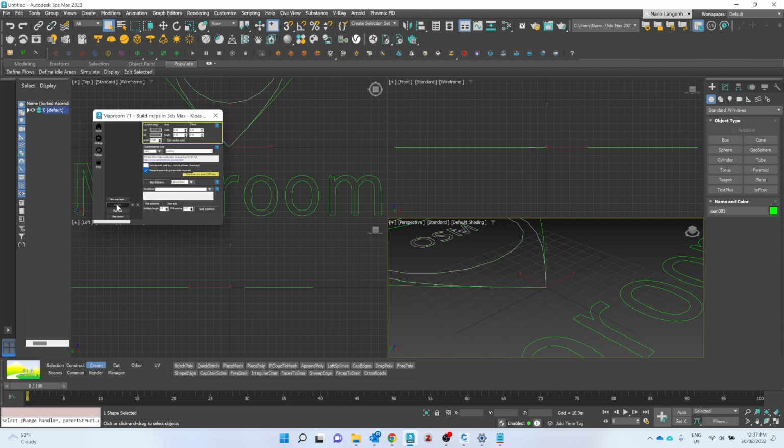I'm going to come into OSM, my single OSM layer, and I do like to layer these up, so new map layer, I would do this for each separate piece of geometry. And here I'm just going to take the layer buildings. I'm going to leave it as 4 kilometers by 4 kilometers because that seems to be working pretty well. And as usual, I just press the download and draw the OSM layers. So you'll see that's doing its thing at the bottom there.